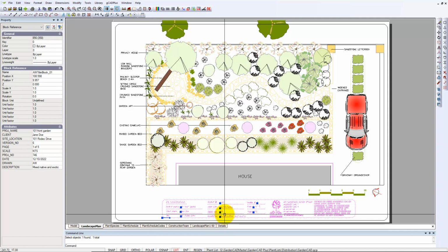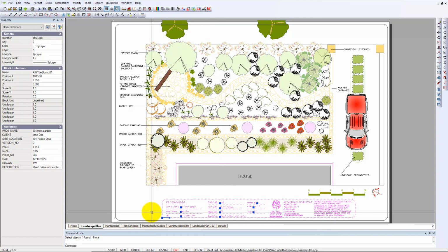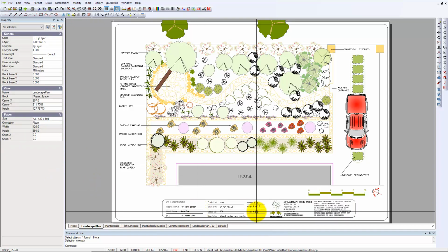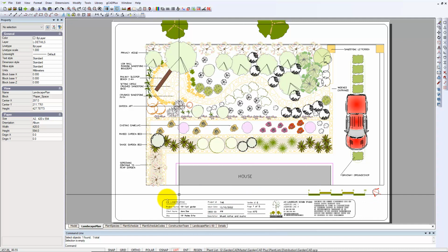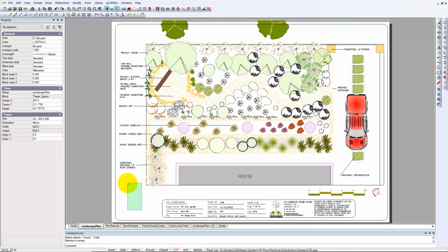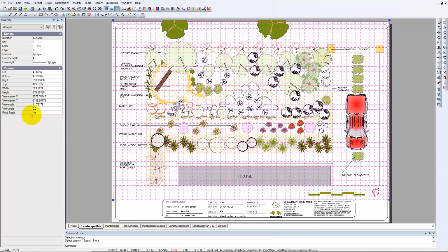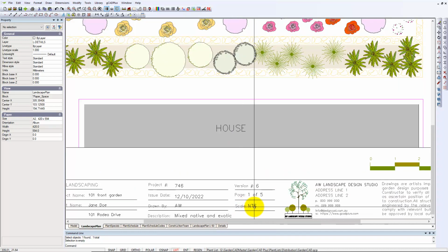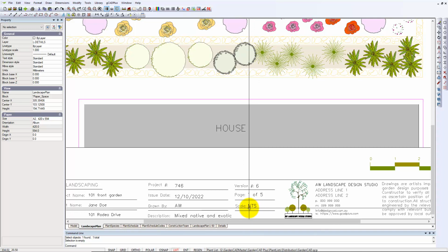put a title block down here. It's a title block that contains attributes, so we just fill out information here and that information will be transmitted to that title block. If I select the floating viewport here, which I think is able to be selected, and I've got it now, the view scale over here is 41.721, so it's in fact not to scale. It's not a fixed scale, and there are times, and we've put an attribute in there and just entered NTS there.